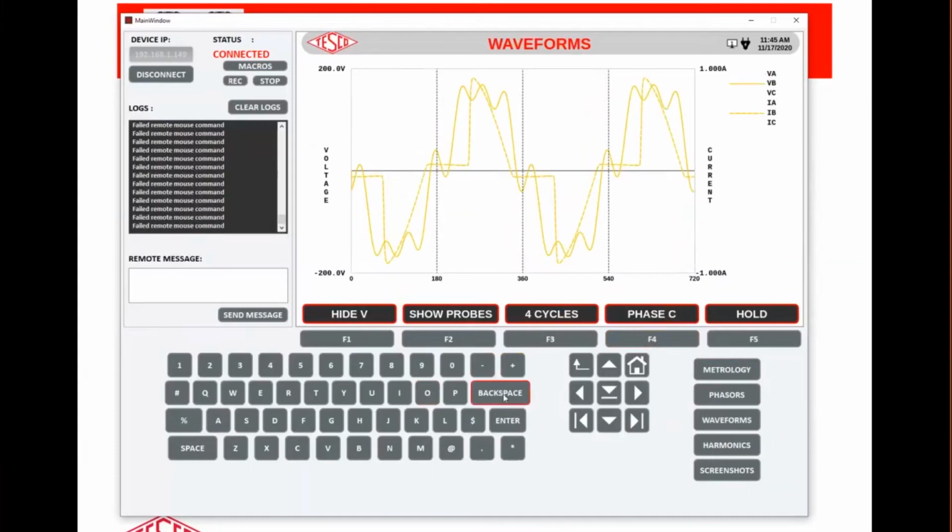The current waveform is the waveform that we talked about as basically a phase-fired waveform. This is when you control power to a device by literally turning off the current using a SCR or triac for part of the waveform.